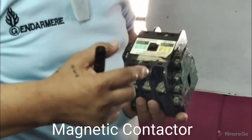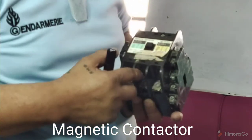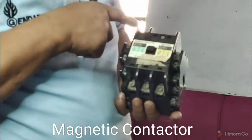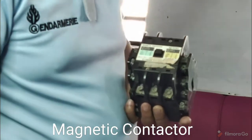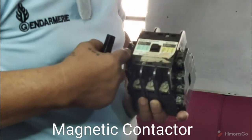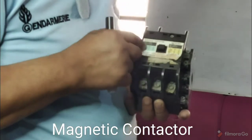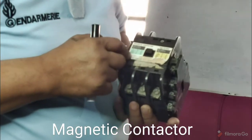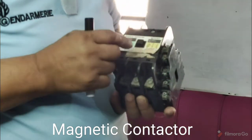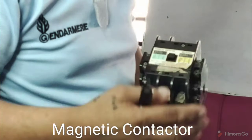Then if you ask me, sir, how about if the line voltage is 440 and you have only 220, then the motor is rated 440. So, of course, the power is 440, but the control circuit of your starter is only 220, then we will be using a control transformer. So again, I will explain that.